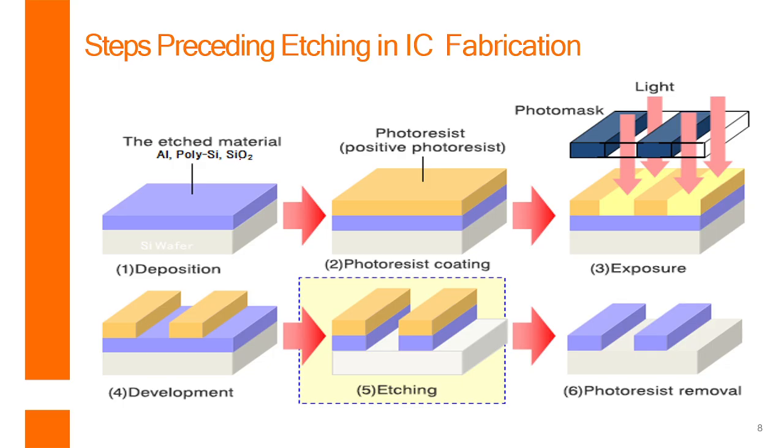Mainly first we are using silicon dioxide only, SiO₂, and on this you need to keep photoresist material, and after that with the photoresist mask you will pass UV light. When you pass the light, this area is covered, this area we want, so this area will not be etched. Whatever this area is, this area will be etched.